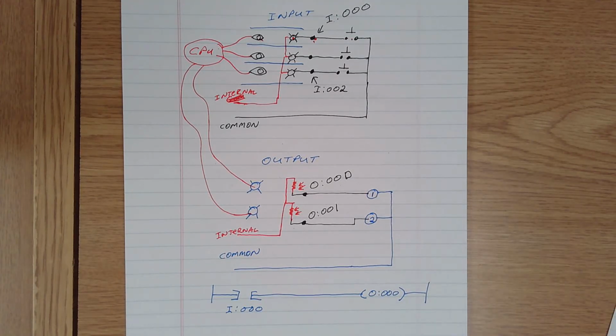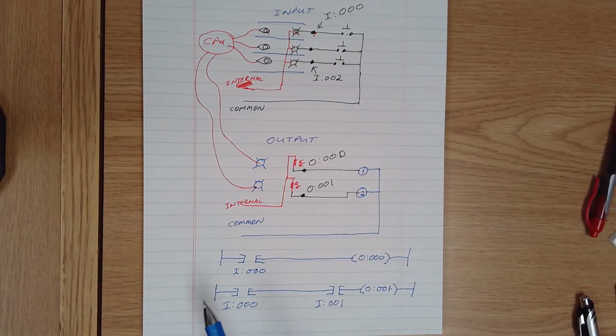Okay, so that's what's going on inside the PLC, and that happens every time the PLC goes through its scan cycle. Well, what exactly is a scan cycle? In your lines of logic, which is what we've programmed into the CPU, what we want it to do with all of those instructions, the CPU goes through the first line of logic, sees input 000.